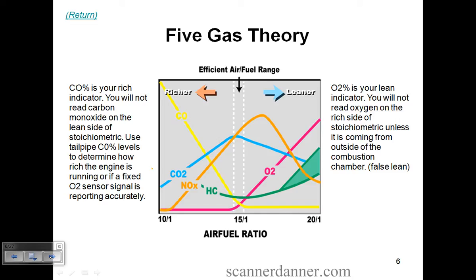Meaning, if I have my CO measurement, I know which side of stoich I'm on. And if I have my O2 measurement, I know which side of stoichiometric I'm on. Can I say that with hydrocarbons?